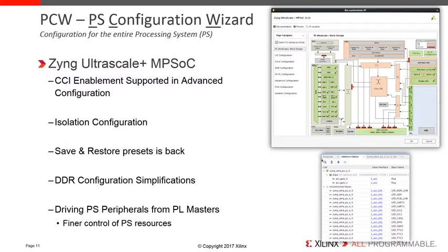Simply speaking, you can inhibit AXI transactions between a master and slave based on the settings of the XMPU and XPPU.